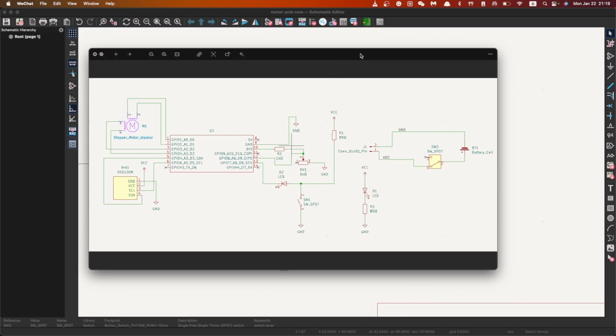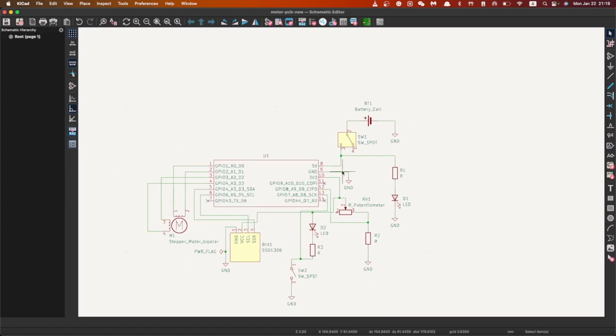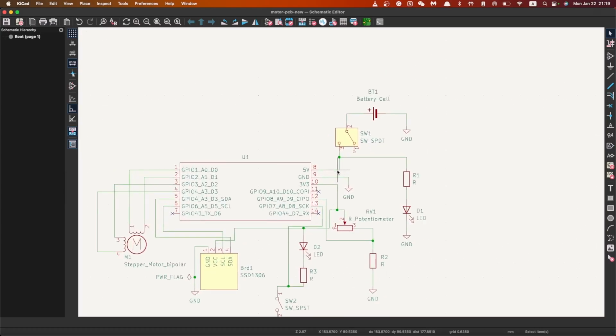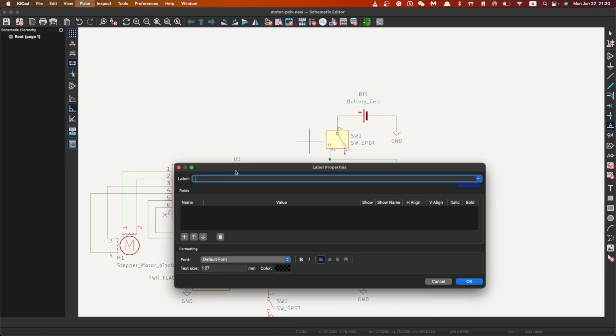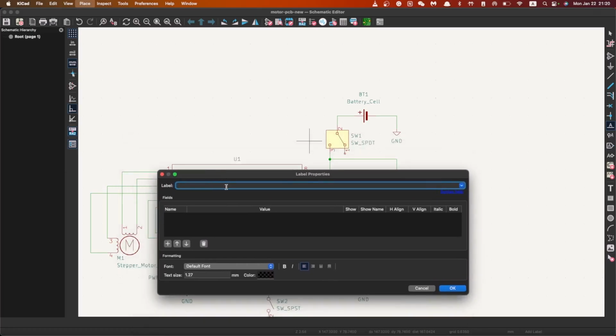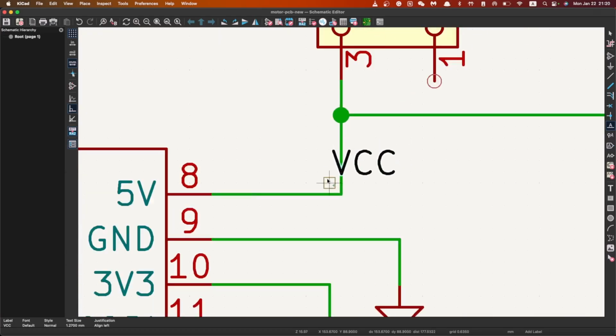so what I want to do is to give these VCC some names or labels. As I kept saying labels, labels, labels, you might guess that the shortcut key for creating labels is L. Okay, so hold on a second. Press L, and here it is, a label window. And we'll say VCC, press OK, and you can see that there's a square here.